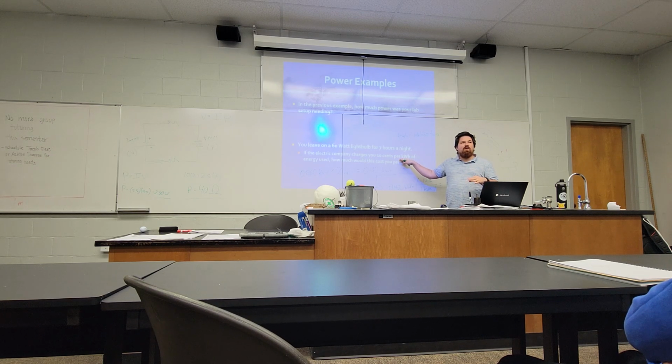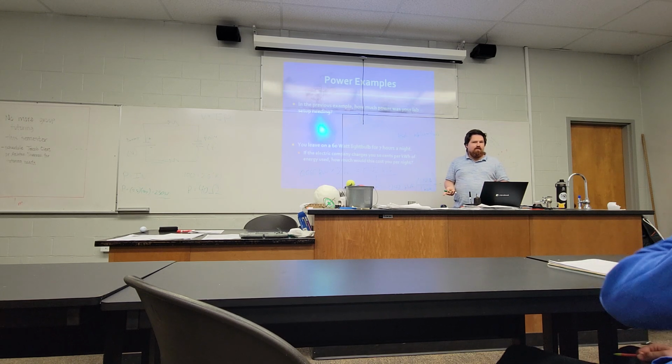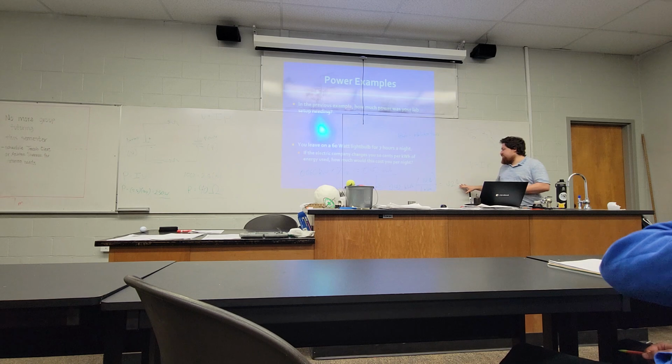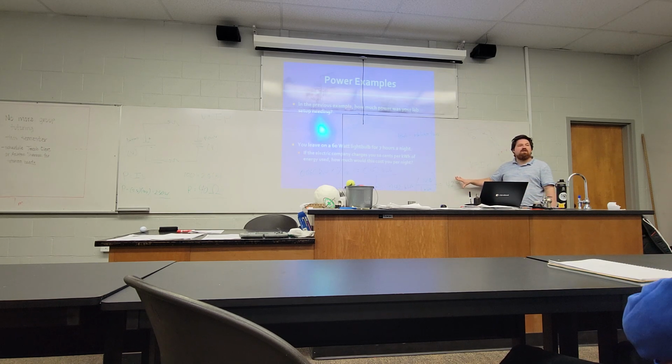Again, South Carolina, the going rate these days is, I'll round it to 13 cents per kilowatt hour. So it might be about 5 cents these days for this light bulb, but that's for a 60 watt. Most bulbs you get these days are about 20 to 30 watts. So like 2 cents, 2.5 cents to have a light bulb on just for the dark hours.